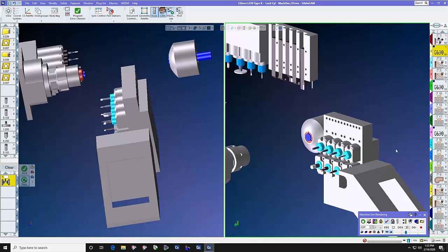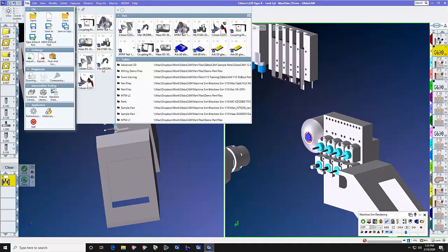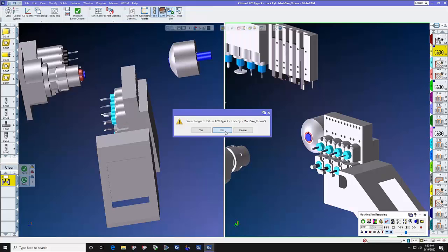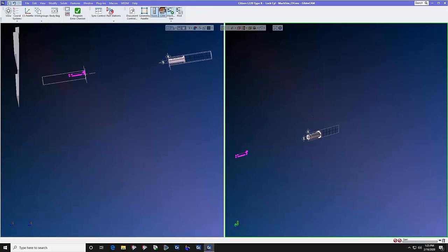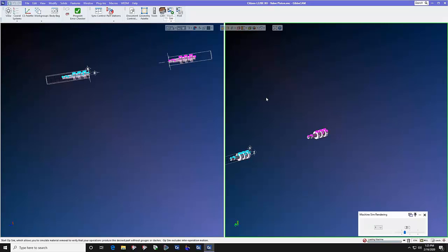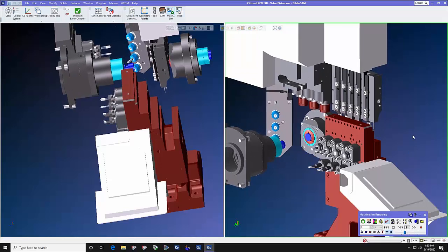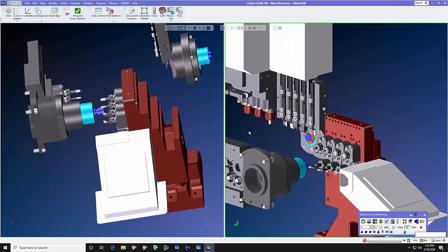The Swiss machines also come in many different flavors. There are Swiss chuckers, and Swiss machines are now approaching another stage in which they have decided to go back to turrets on certain types of machines. The ECAS machines had a turret, and now Tsugami has a third generation of machines that have a turret on it, where this is a gang style machine with a B-axis.